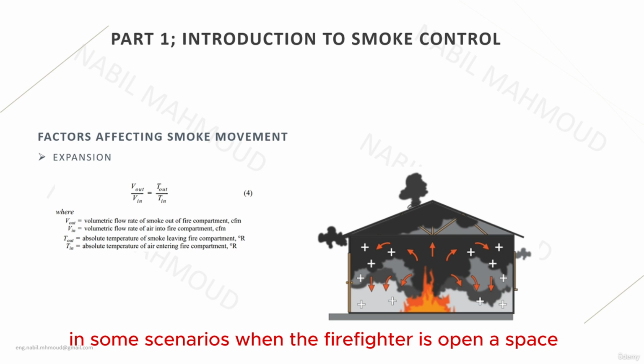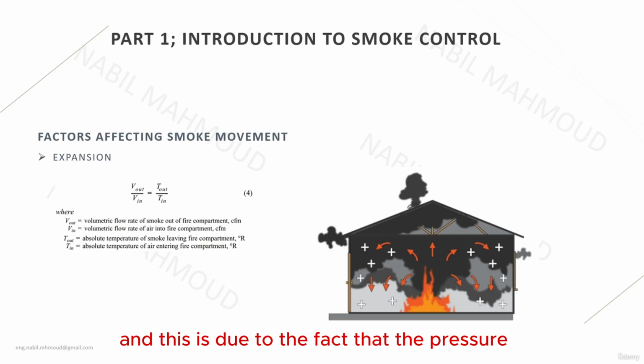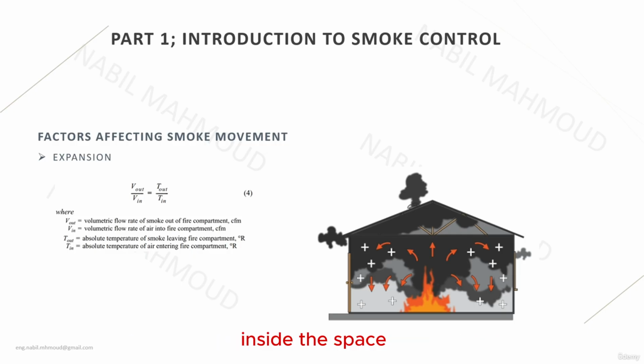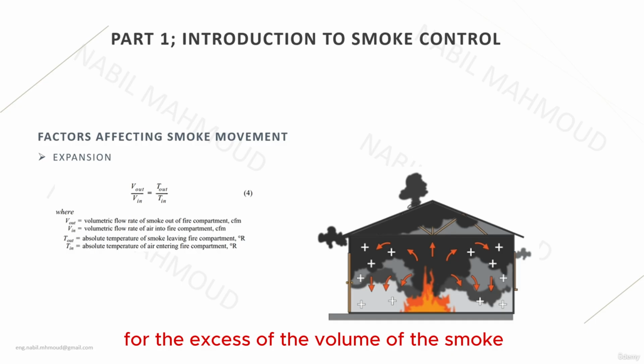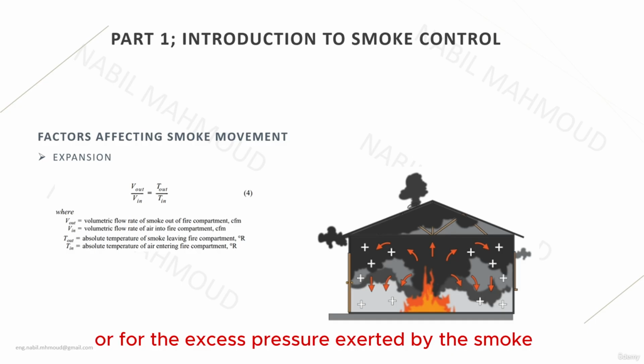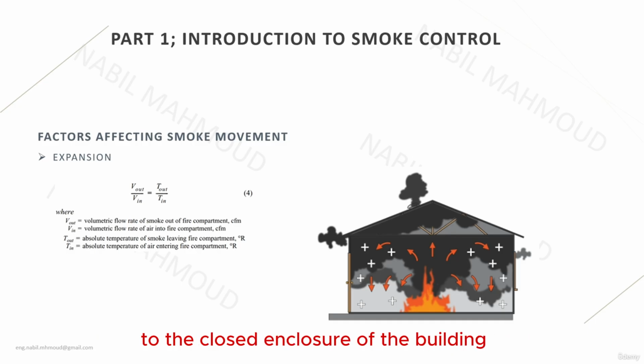In some scenarios, when the firefighters open a space, it explodes, and this is due to the fact that the pressure inside has increased significantly due to the expansion effect of the smoke inside the space, while there is no ventilation or venting for the excess volume of the smoke or for the excess pressure exerted by the smoke on the closed enclosure of the building. And this is a very dangerous phenomenon that needs to be studied and evaluated.